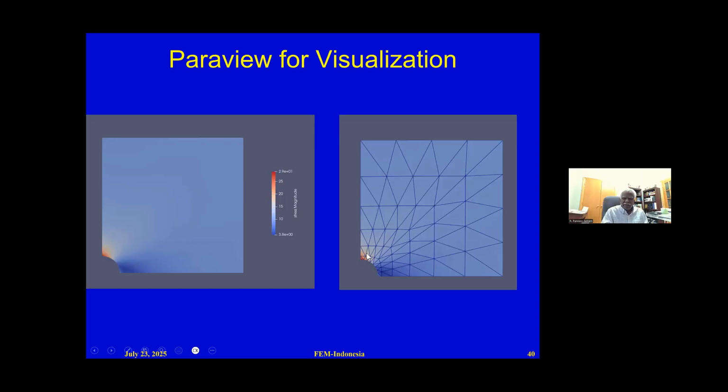You can see that the maximum stress concentration is about 3 times the stress around here. The model is able to capture 2.9; you can see the number 29, whereas the applied stress here is 10. You can see the colors. It is supposedly 3 times the value, so there is about 3% or 5% error, but it is reasonably predicted. So this is a contour plot, and this is a grid, which you can also draw.